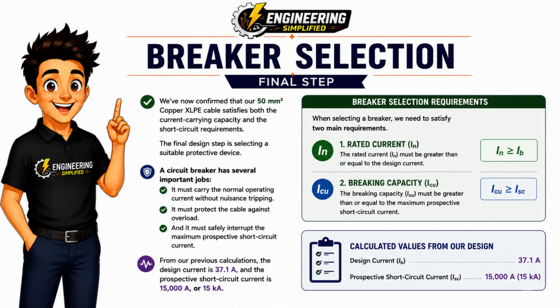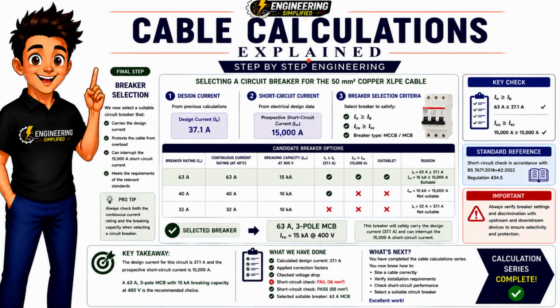First, the rated current, In, must be greater than or equal to the design current. Second, the breaking capacity, Icu, must be greater than or equal to the maximum prospective short circuit current. Let's compare a few possible breaker ratings. A 32 amp breaker is too small because it cannot carry the design current.